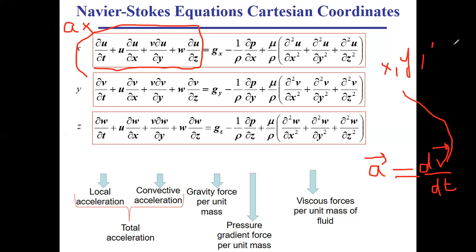So you will use the concept of partial derivative, and you can establish that the derivative of a certain vector with respect to time, this is called the total derivative, is equal to the local derivative, and we'll explain the physical meaning of the local derivative, plus the derivative related to change in space. So this will represent variation with respect to space. So what is the meaning of local acceleration and convective acceleration?